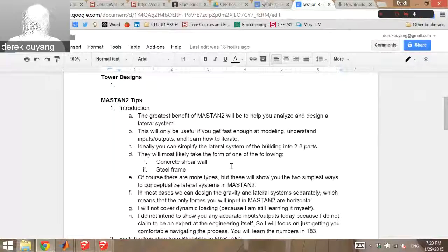Once you've run the analysis and you're looking at the results, what else is important? Flexion. So that would be a serviceability check, but that doesn't necessarily get you the size of the member. Moment diagram. Yeah, moments. So then basically what you tend to look for right away is what's the maximum bending moment anywhere in your structure. And it's usually going to be right at the base for a column. And so that's going to determine the stiffness of the member and bending in the strong axis or the weak axis. So those are really the key things you're going to look for.